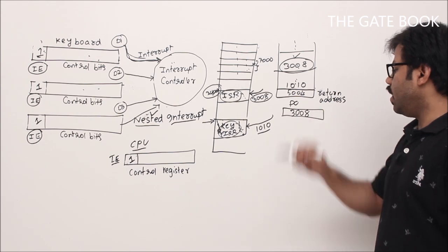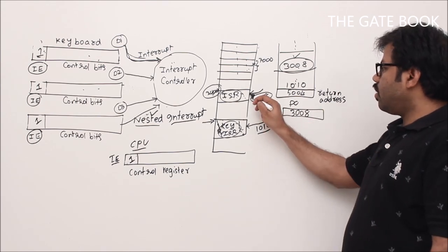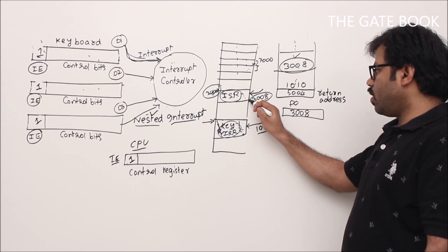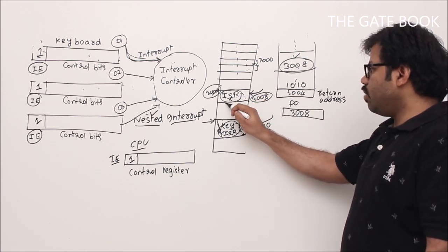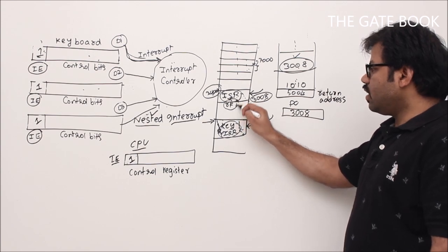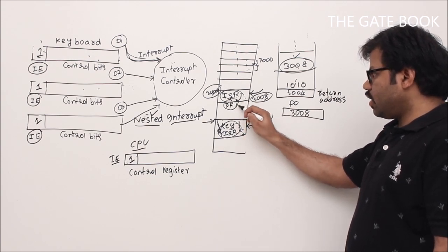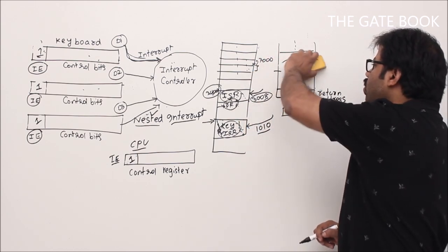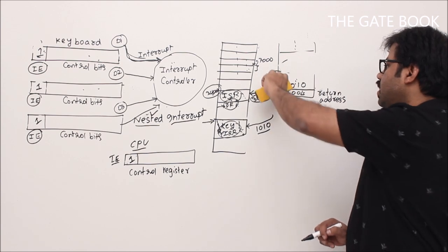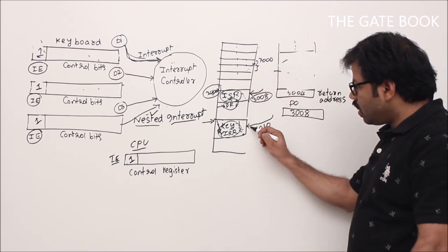Fine. Okay. Then blindly that processor will execute this program, right? While executing this one, once this interrupt service routine is done, there will be a return from interrupt, right? So whenever this return from interrupt is executed, what it should do is pop one more return address, this time 1010. So because of that, control comes here.